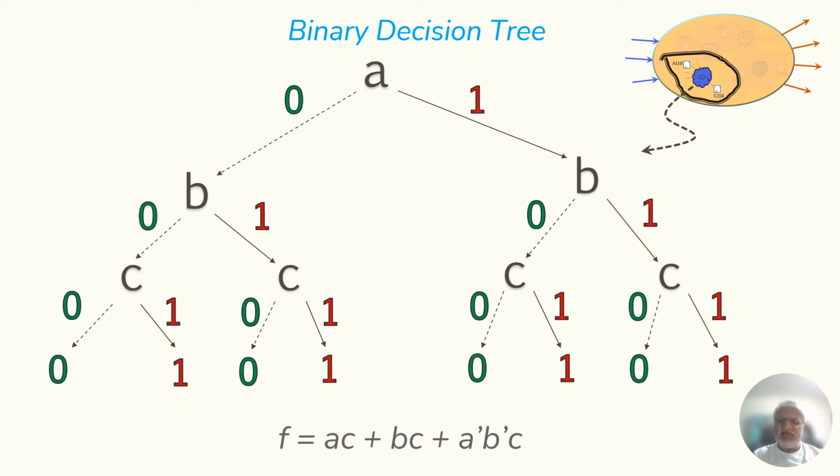This is done for the same blocks which are part of the golden design, and for the same cut points for the revised design also, though the equation need not be exactly the same. So for that also the results are figured out. Then the results are compared through the XOR. If the results are equivalent, then we will say that these two blocks found through the binary decision tree for the golden and revised designs are the same.